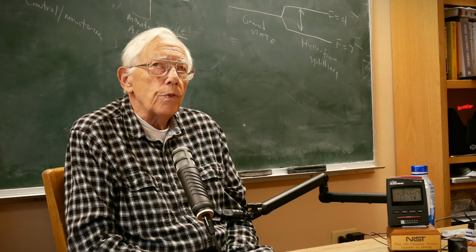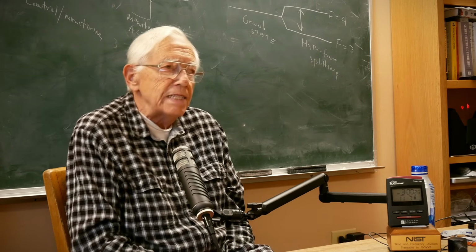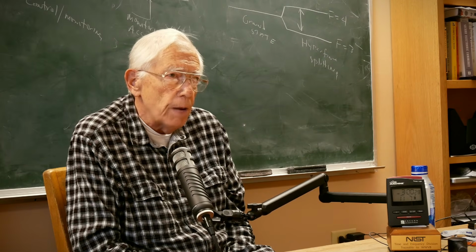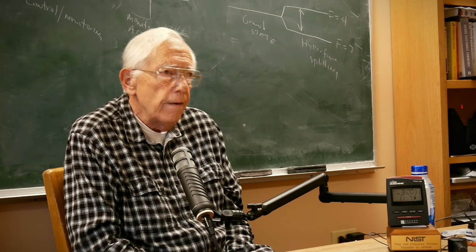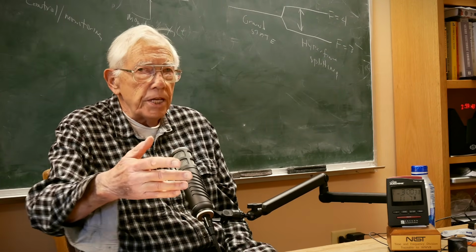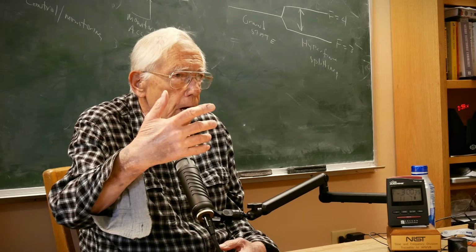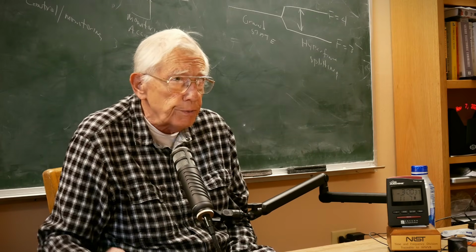I think it's also a good question, how to precisely measure frequency. Well, normally the way you precisely measure frequency is by measuring time interval. Let's suppose you have a frequency which you claim to be a megahertz, 1 million cycles per second.